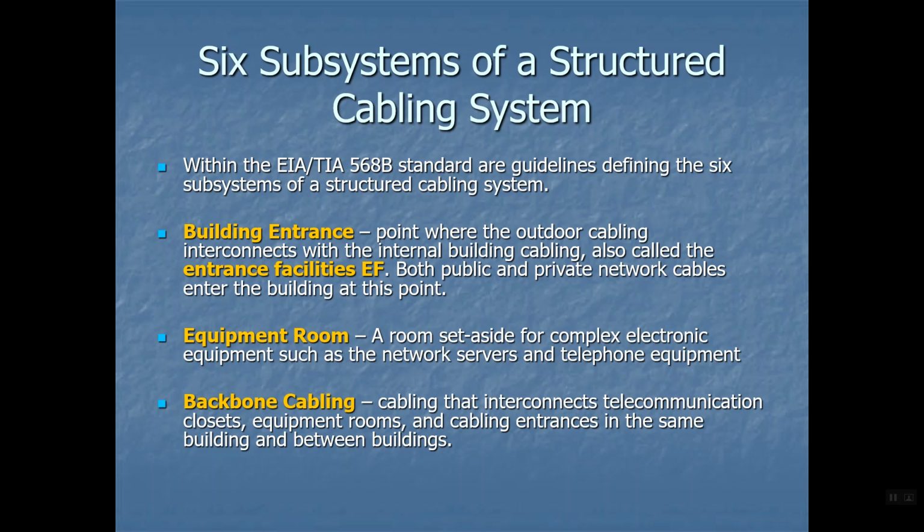There are certain details that you have to be aware of, and one is that the service cable that comes in from your service provider cannot be in the building more than 10 feet.